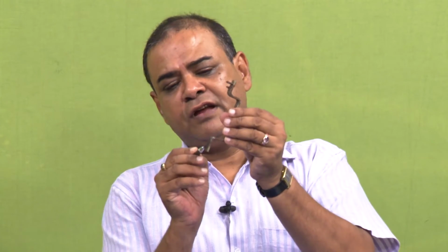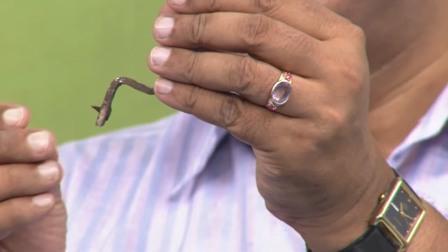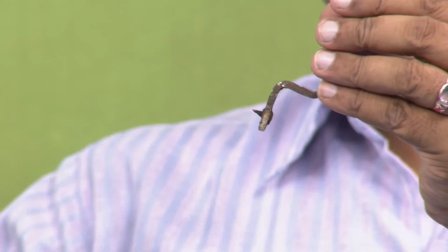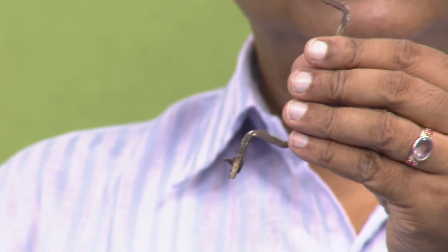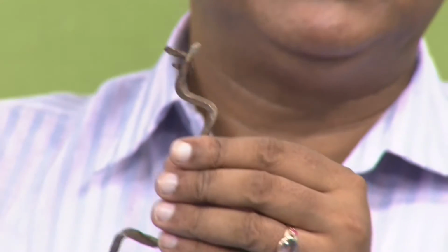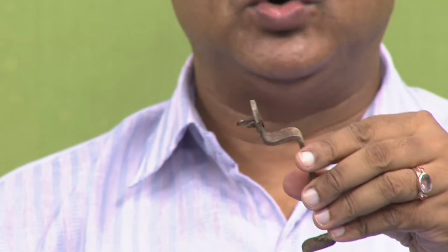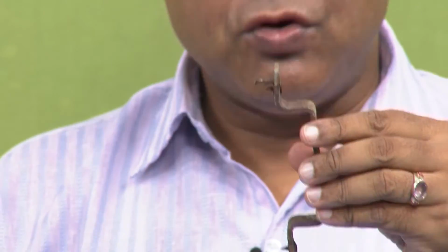And if you see this one, some part has vanished because the corrosion was so severe, it got lost into the atmosphere, though it remained in the wooden part because it was fixed like this on a wood. Now why is there a little bit of corrosion on top, but the part which has entered into the wood has a lot of corrosion? This can also be explained by using this concentration cell.